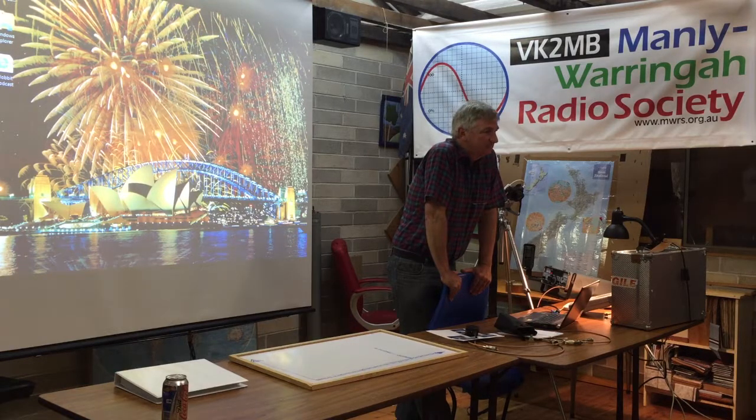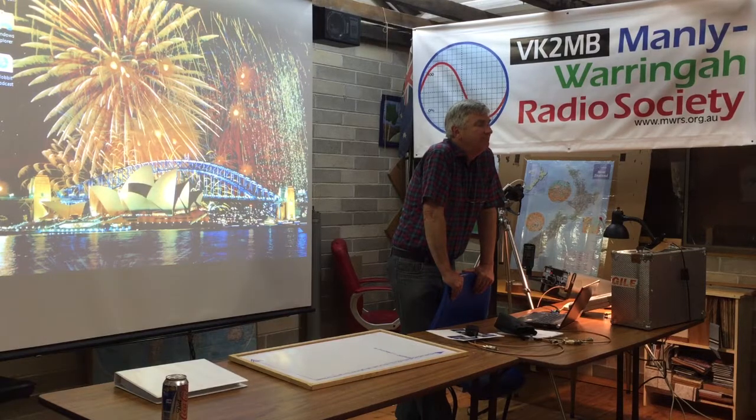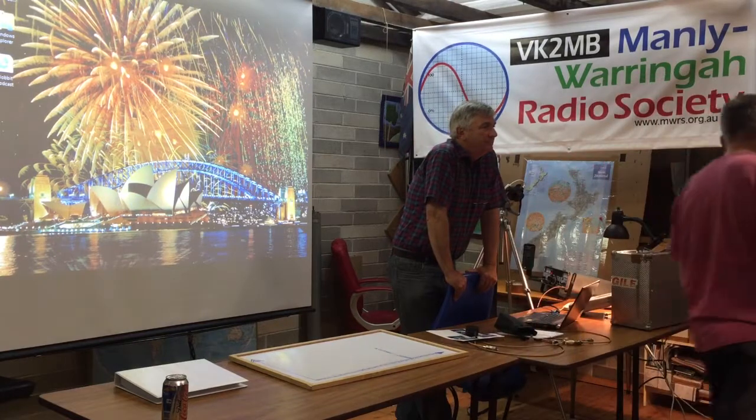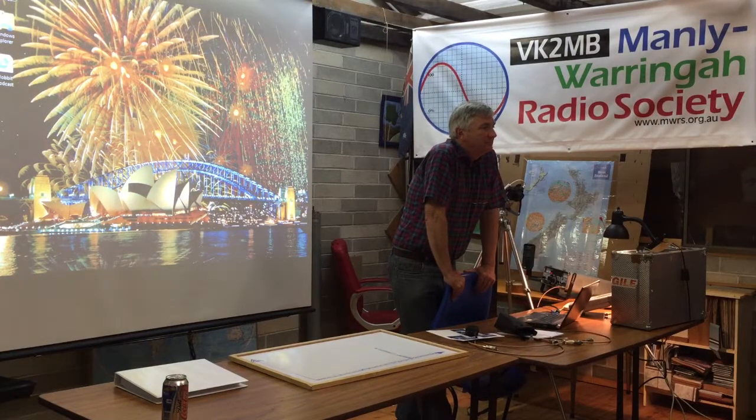In some of the receivers now, we've got this thing of transmitting Ethernet over 160 kilometres with about 3 megabits per second on a 900 megahertz ISM band. They're actually using a spectrum analyzer live to analyse this chirp spread spectrum, to analyse each frequency, and it applies an individual noise blanket to that frequency if it sees something dynamically using it. So it's actually a real-time spectrum analyzer analysing the entire band and applying noise blanking.